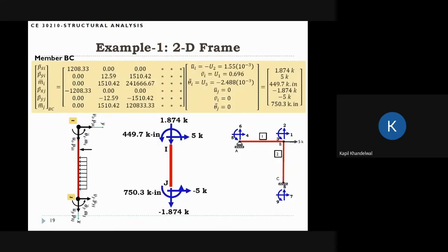In this case, we actually have to do the calculation because the stiffness matrix in the global and local systems are different. So we have to find the stiffness matrix in the local coordinate system. So this is the stiffness matrix. I didn't write down all the entries in the stiffness matrix. It turns out we don't need the last 3 columns, so I didn't put those entries. And we'll see in a moment why we don't need them. Turns out these last 3 columns get multiplied by 0.